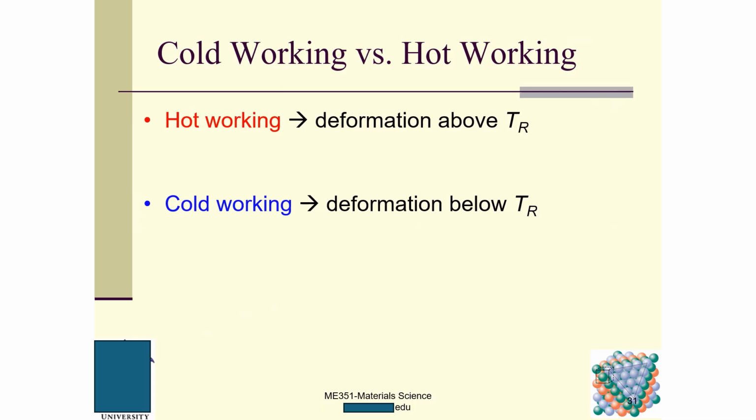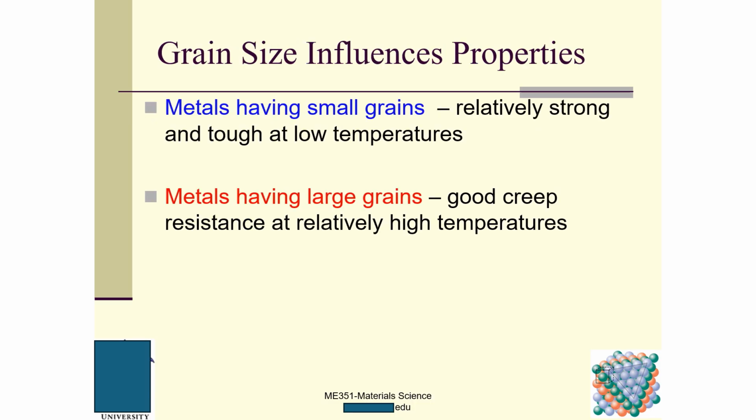And then we talk about cold working versus hot working. Both of them are working. In hot working, the deformation occurs above the recrystallization temperature Tr, and cold working means the deformation occurs below the recrystallization temperature.